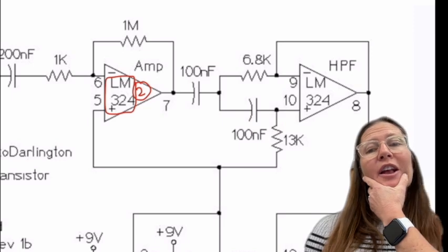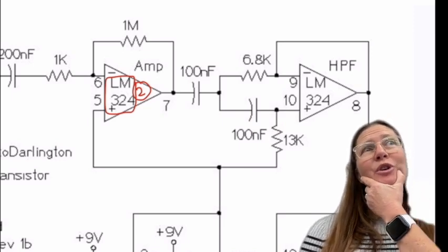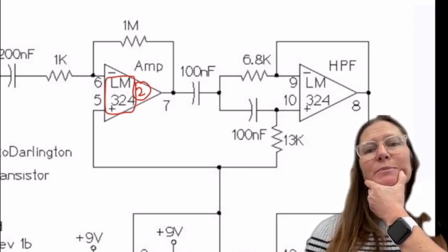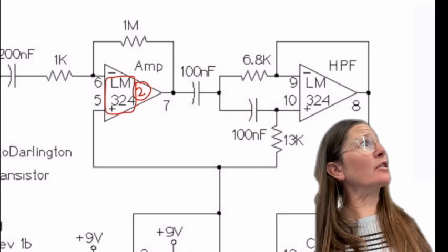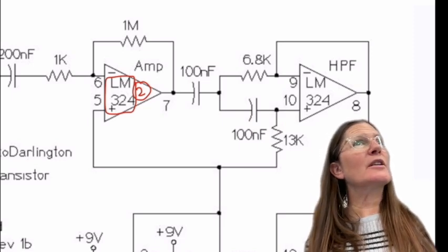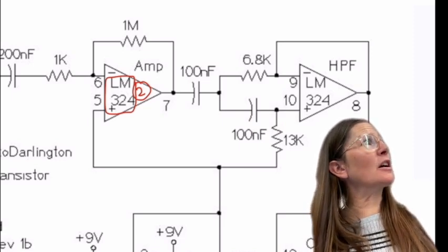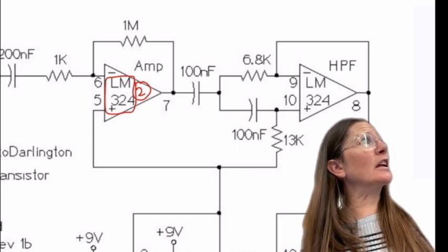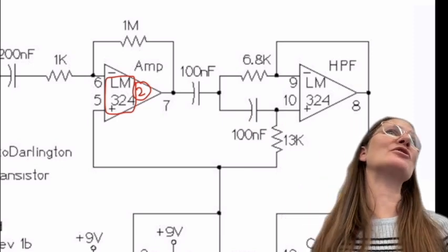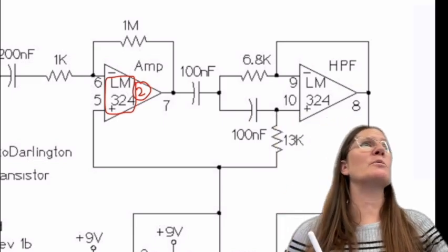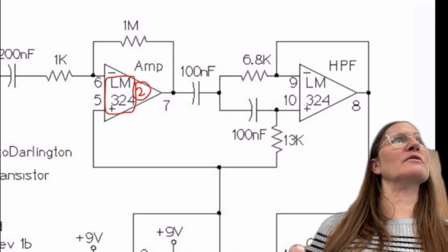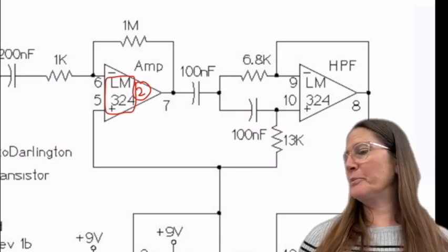So it filters, so it doesn't change. This is still going to be a... So that's actually a buffer over there. On the far right, that's going to be a buffer voltage follower, and then the capacitors in there are going to create which frequencies are actually going to go through to it. So it's called a high-pass filter, and it will pass frequencies above a certain value.